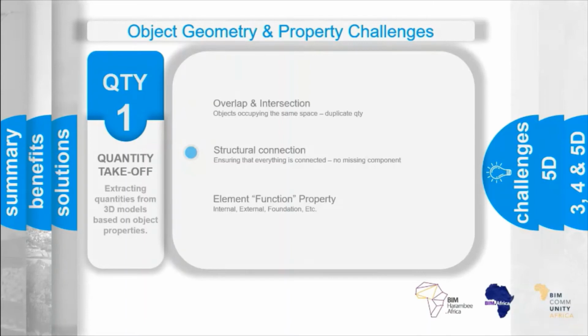Likewise, structural connections. Note that all modeled objects should be connected. Nothing should be floating. That is to say there shouldn't be any gaps between objects, because a gap would imply a shortfall in the quantity of one or more of the modeled objects.